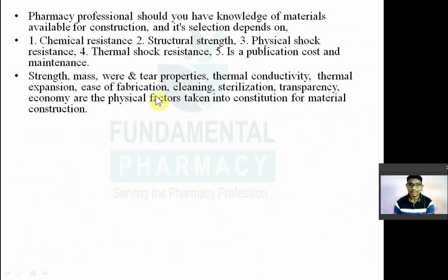It should have high thermal conductivity, which is desired if you are designing the equipment for heat transfer mechanism or heat operations. In that case, thermal conductivity is desired. But if you are not designing for heat operations, then thermal conductivity is not much important. Then thermal expansion should be less.